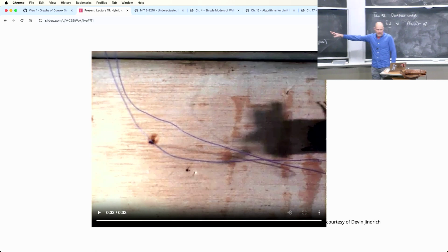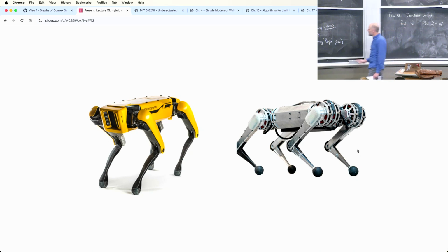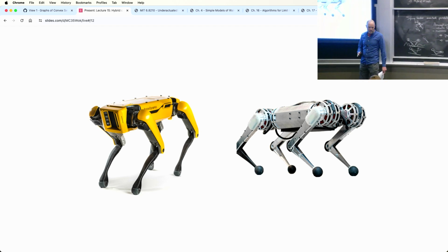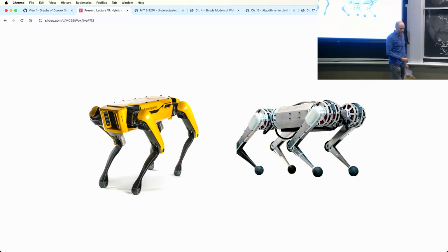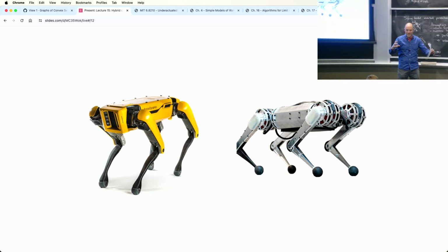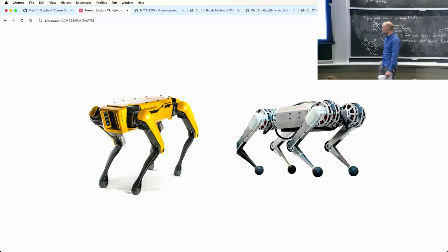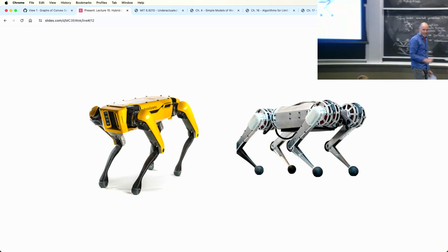Okay, so that's animals. Maybe you don't care about animals, right? I mean, you should care about animals, but when people ask why quadrupeds work so well lately, I think there's a couple stories. I do think control has gotten better. That's true. But I actually think one of the things that people underestimate is that the mechanical design of our quadrupeds changed dramatically. Spot was one of the first, but if you look at all of them nowadays, everybody figured out you want a relatively massive torso with some inertia, and you want super light legs, right? Limit as mass approaches 0. Why? Because if you can move your legs super fast, then it's pretty hard to fall down.